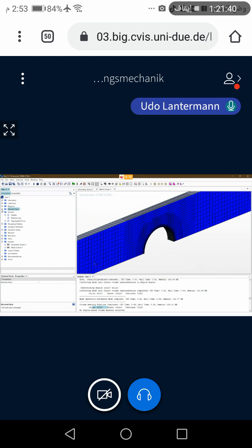Okay, that's all of the derived parts. Next one is solvers, but for solvers we take the default values. For instance, for steady, there is no option for partitioning. Also, we choose the default one, and then we use this segregated flow, and we will change the parameter, the under-relaxation factor of the velocity.